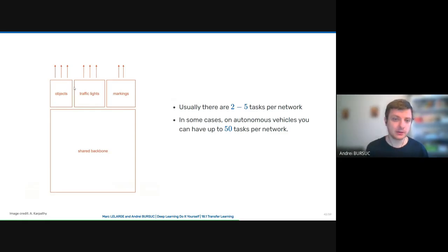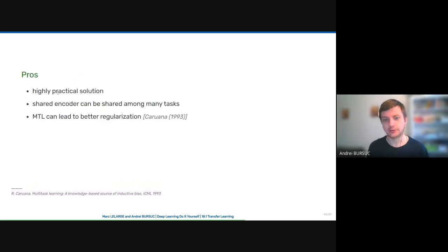Then, for example, let's say that we train just for traffic lights, you can freeze the backbone and the other heads, and just train this head. And then add this head with the entire pipeline frozen. Then you have these Hydra networks with many heads that work fast on the car.